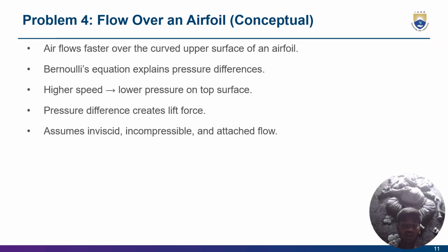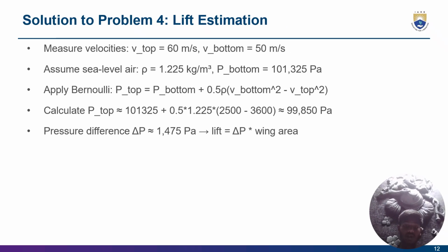Lift on an airfoil. Air flows faster over the curved upper surface of an airfoil, and Bernoulli's equation explains the pressure difference. Higher speed means lower pressure on the top surface. The pressure difference creates lift force. It assumes inviscid, incompressible, attached flow.